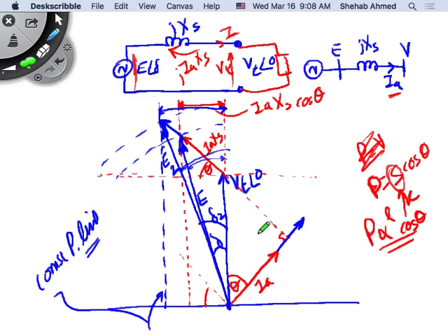The other condition is, these cables are in ambient conditions. Ambient condition is 50 degrees C, and I'm going to pass current through them. And these cables have losses, I squared R. So the cables will heat up above the ambient condition. They're already at 50 because of the 50 degrees Celsius ambient, then they will heat up another 50. They can melt down the insulation. So all electrical apparatus really has a limit based on physics, and I think we discussed it in 438, even power devices. Everything will break down because of physical phenomena, like voltage in this case, which needs insulation because of the breakdown of the dielectric, and heat.